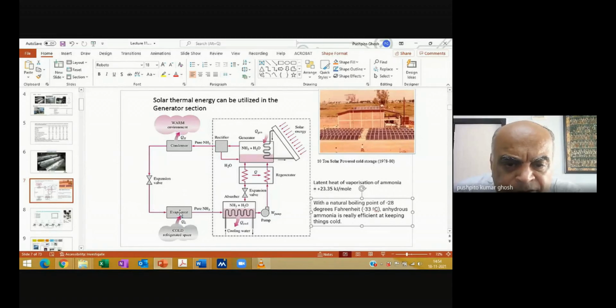So you can imagine that there is an evaporator, so it's evaporating the ammonia which is in a liquid form, and this is getting cold. It can keep cooling down because the boiling point is low. Obviously I need to keep this liquid at that kind of temperature, so that's important.